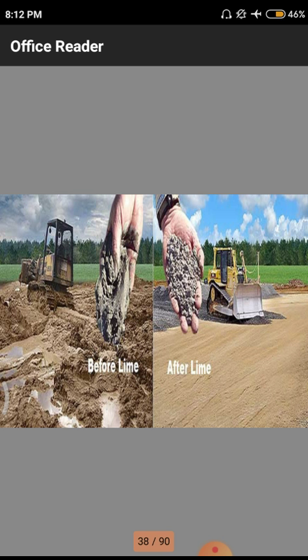Here also, consider how the soil behaves before spreading lime. After spreading lime, the soil behaves in a very smooth manner with some binding properties, without absorbing water. But in the previous case, the soil has a huge amount of water, and there may be some sinking of vehicles. That means the construction equipment is also sinking in the soil before lime. After the lime, the equipment moves in an easy manner.